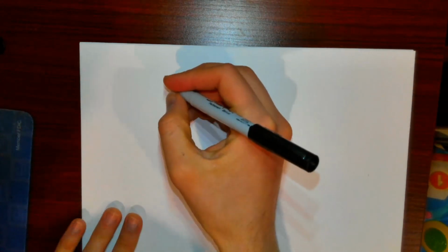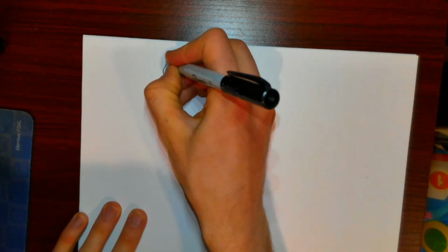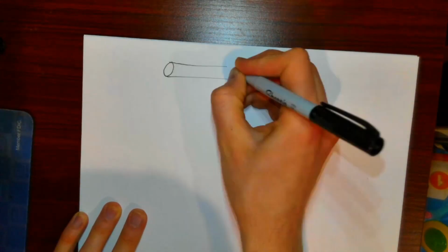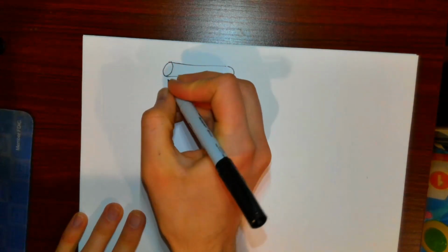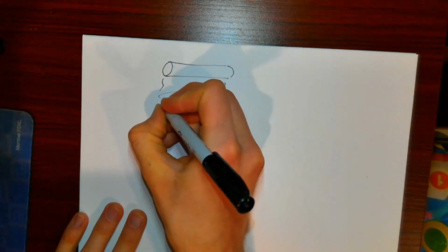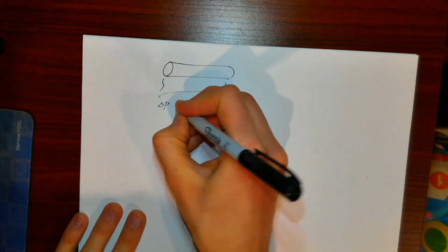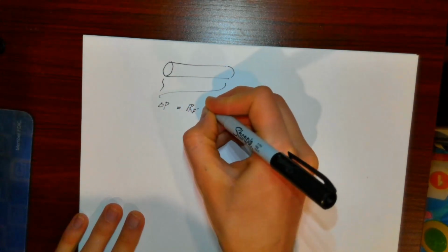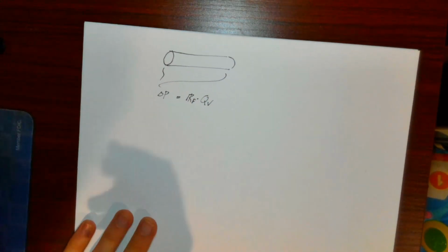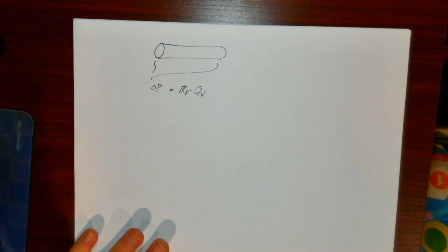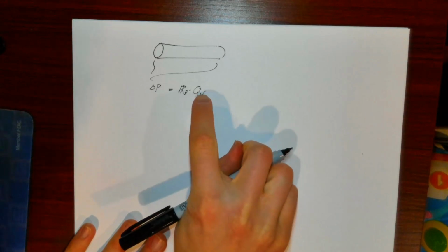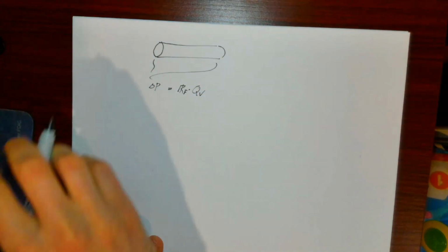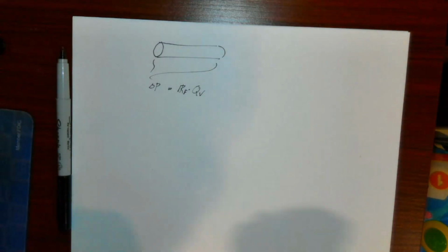So what do fluidic resistors say? Well, fluidic resistors basically say, hey, the pressure drop is equal to the fluidic resistance times the volumetric flow rate. And so if we doubled the volumetric flow rate, we would double the pressure. I could also basically consider